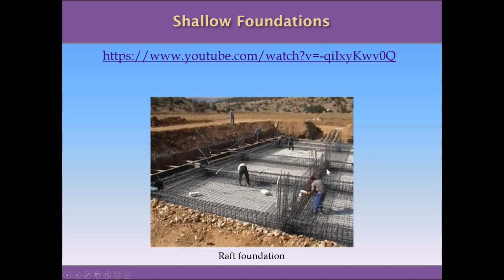As you see, the raft foundation is not a very popular foundation because it's very costly. It's costly because it takes a lot of material, a lot of concrete, a lot of reinforcement, because this is basically the size of the building that has to be founded directly on the ground.